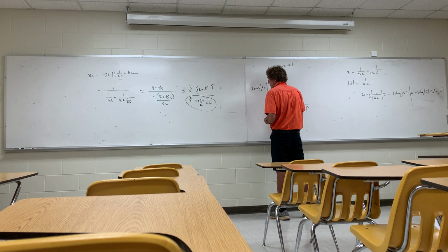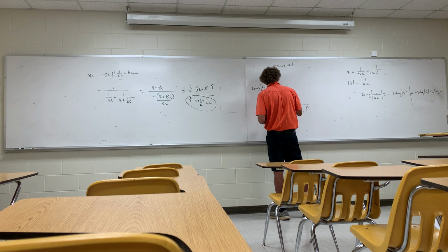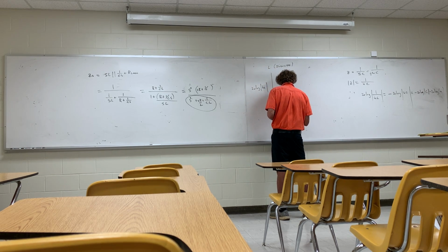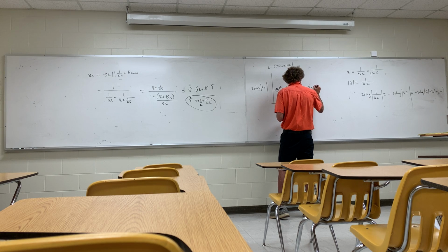It's going to come in at zero. It's coming up at a rate of 20 dB per decade. Then it's going to hit resonance, and F resonance is just equal to 1 over 2 pi square root of L times C. L is the inductance, and C is the parasitic capacitance. And then it falls off at minus 20 dB per decade.